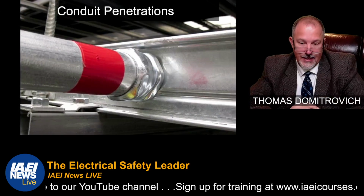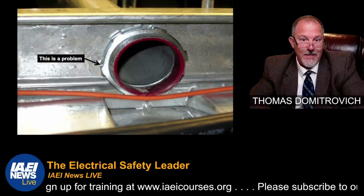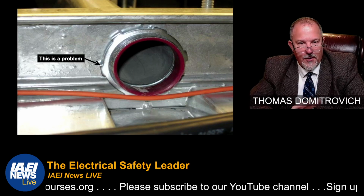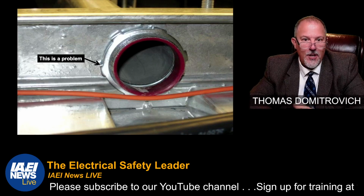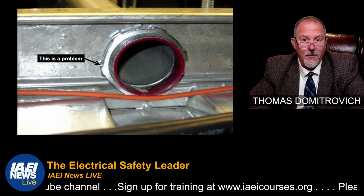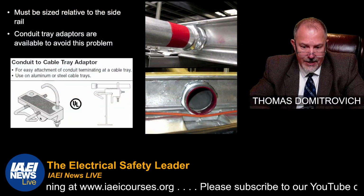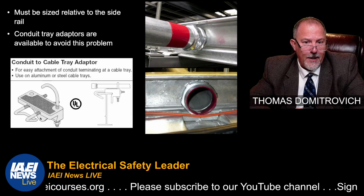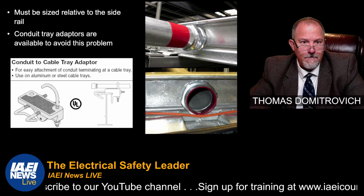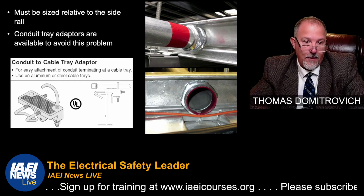Conduit penetrations. Let's take a look at the other side of this installation. This is a problem, right? There's a lot of things going on here. You've got to follow manufacturer's instructions whenever you're penetrating into the sidewalls of a cable tray. I mean, you might hurt the integrity of the cable tray, the structural rigidity of the cable tray. They'll tell you how to put the materials in, how to enter into the cable tray the right way. So your conduit has to be sized correctly and secured correctly.